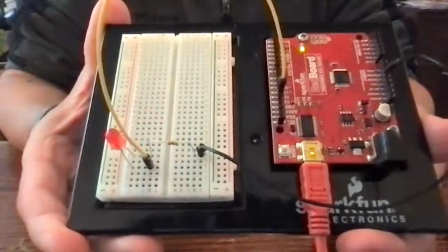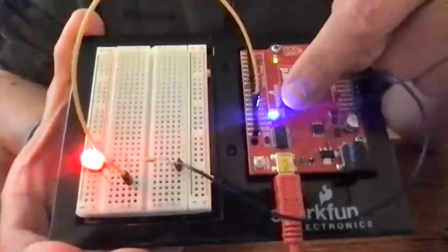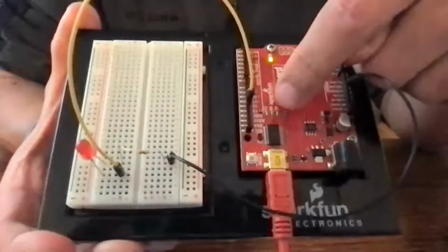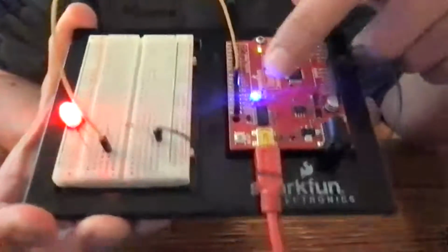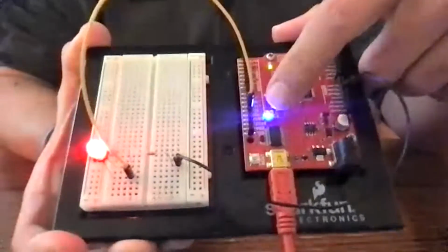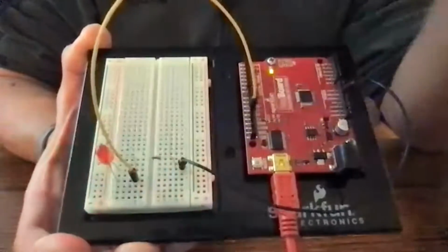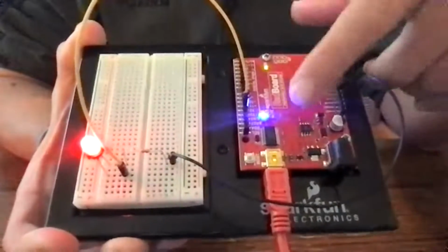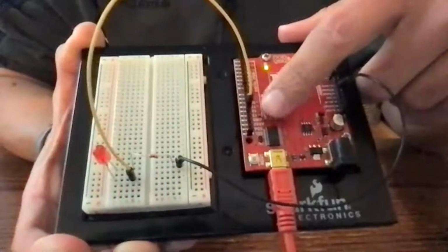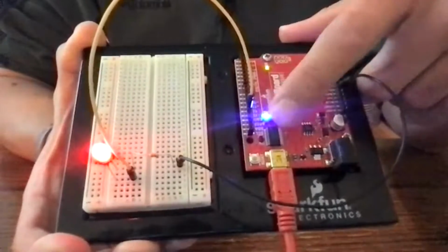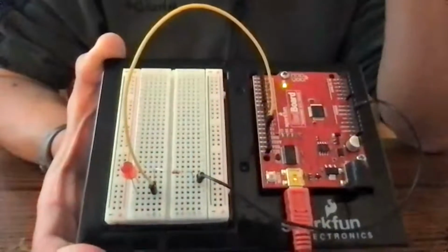So it's pausing 2 seconds in between each time, and my LED is going on. You'll notice also over here on the Arduino board, it's got this blue light that's flashing. On many Arduinos, they have this onboard light, which is usually connected to the 13 pin. If you're using pin 13 and the signal is going on or off, this will flash with it. That gives you a chance to test if it's getting that signal, in case you need to do any troubleshooting with your circuit itself.